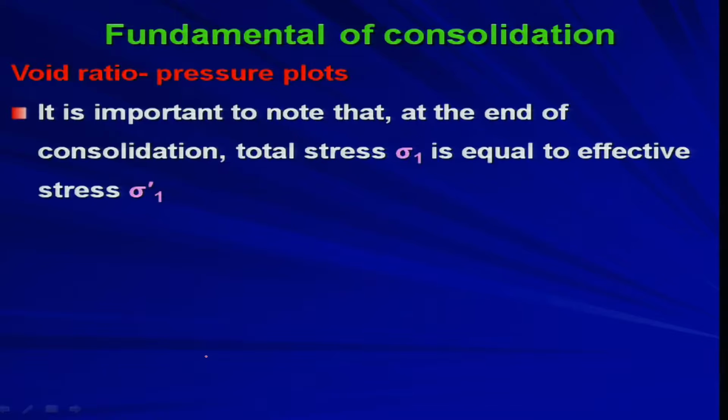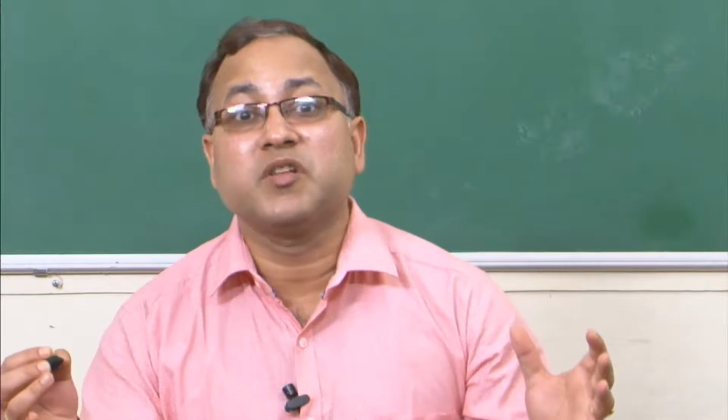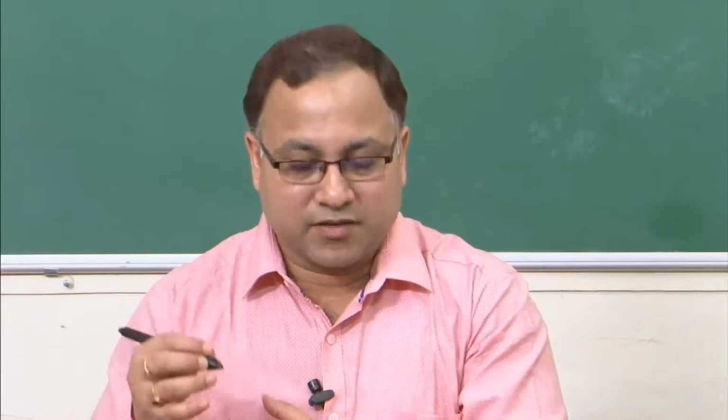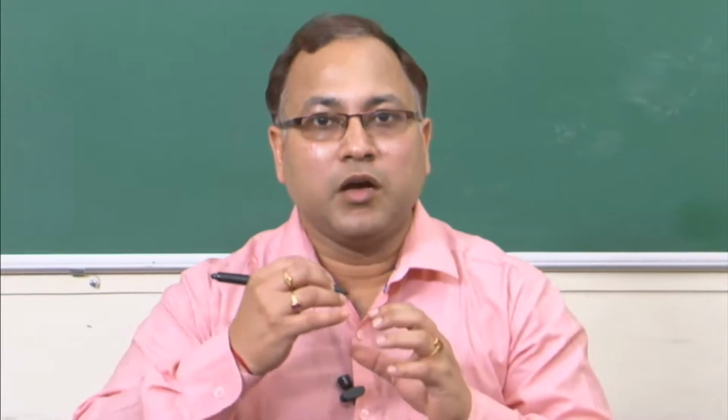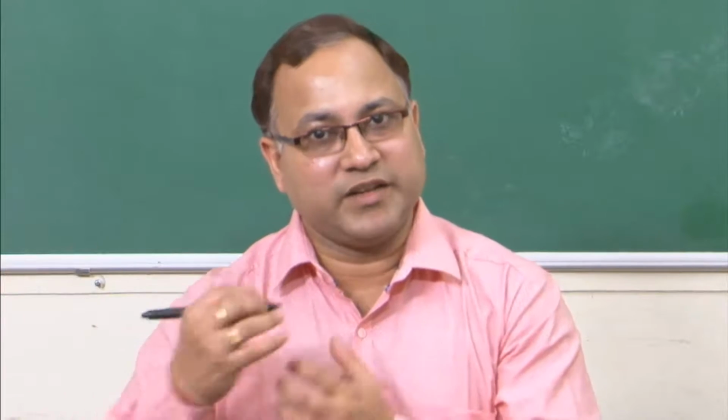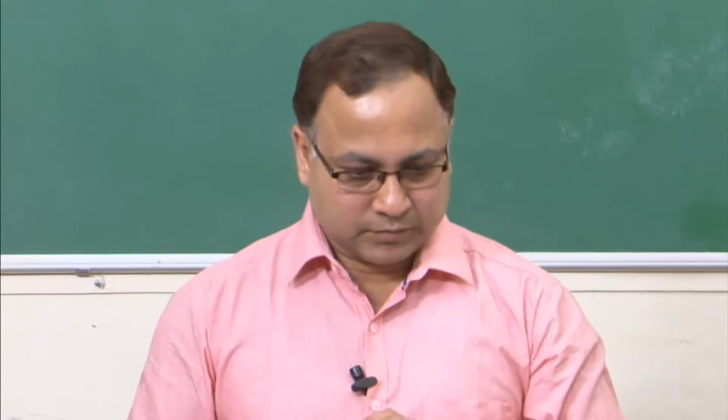So, it is important to note that at the end of consolidation, total stress sigma 1 is equal to the effective stress sigma 1 prime, already we have seen. Ultimately at t equal to infinity, your effective stress must be equal to total stress, because you do not have any pore water pressure built up in the matrix, because the pressurized water will be draining out from the soil matrix.